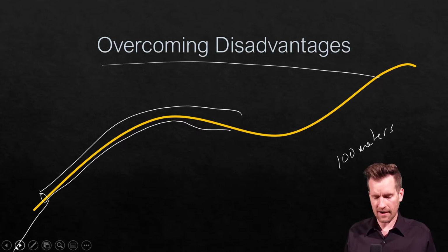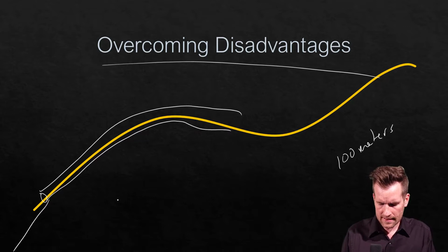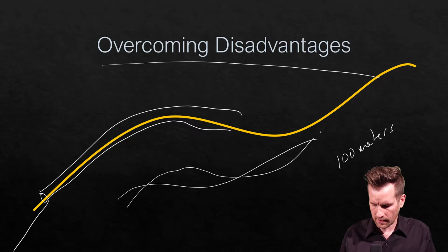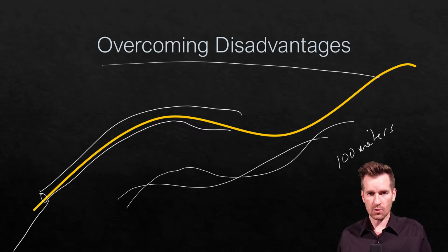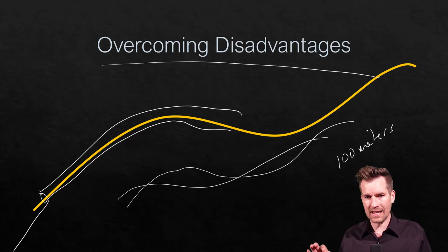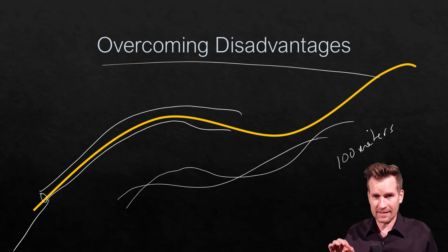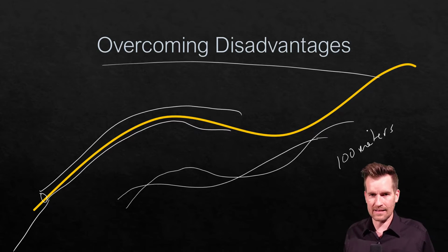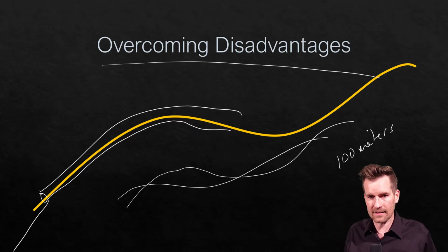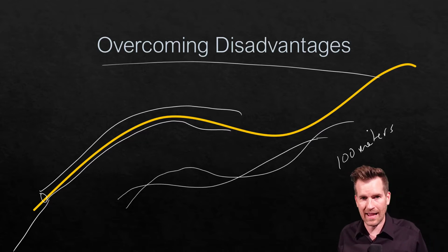Another thing that we've found is that we can take these cables and twist them together and create a twisted pair. When we twist those pairs together, we can reduce the amount of crosstalk that happens. We're going to get much more in depth into twisted pair and what it looks like, but just know that that's another method to reduce the amount of crosstalk on these lines and take away some of those disadvantages that we have with copper cable.